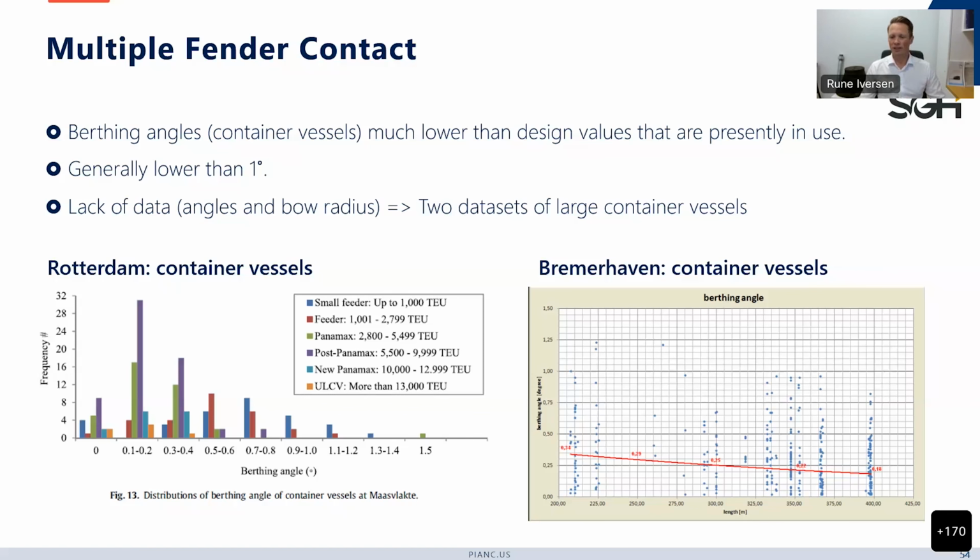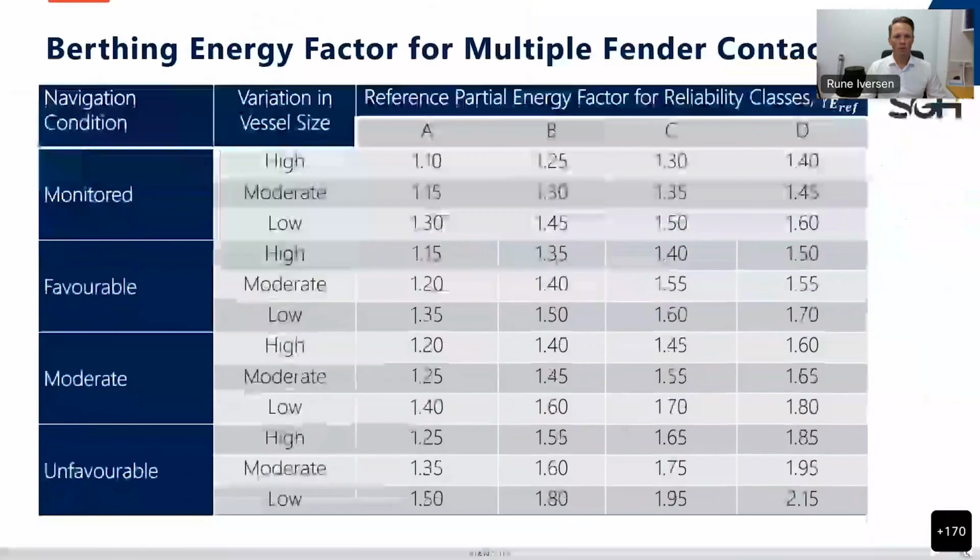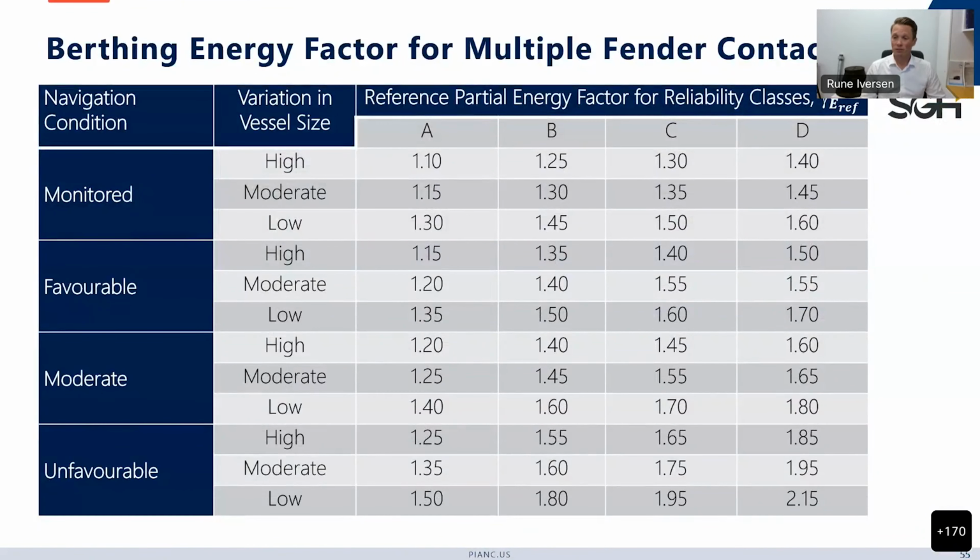After going through a lot of work on this, we have now developed energy factors where you have the chance of multiple fender contact. And again, same table as before, just lower values because you have a good chance of contacting more than one fender coming in.